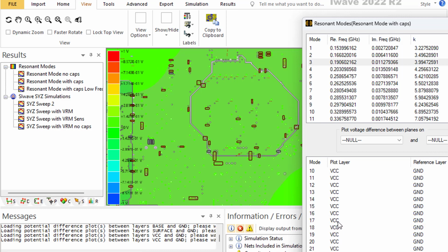9. So now you are asking yourself, we ended up with more than just one resonance. Before we had only one resonance at 200, and now we have more. Yes, adding decoupling caps unfortunately creates more resonances, but these resonances are so small and undetectable. And I'm going to show the Z impedance. You will see some notches, but they are very small, suppressed.